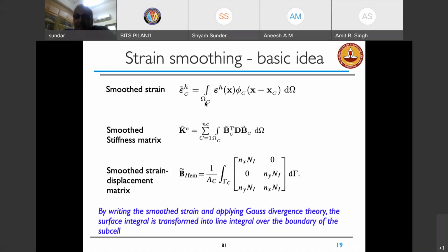So this is a major advantage when compared to other techniques, because you eliminate numerical integration error. You don't need the derivative of the shape function, which implies you can work in the physical space. Since you work in a physical space, there is no mapping involved, which implies you can also have concave elements. Remember, one of the setbacks that we had with finite element was that the elements have to be of good shape. So now all these are eliminated. We can work with concave elements. We don't need derivative shape functions. There is no mapping, and most importantly, there is no numerical integration. So many errors are actually reduced when we use the smooth finite element method.